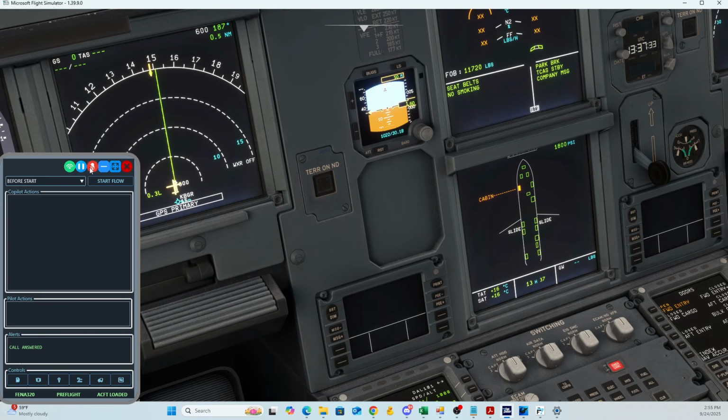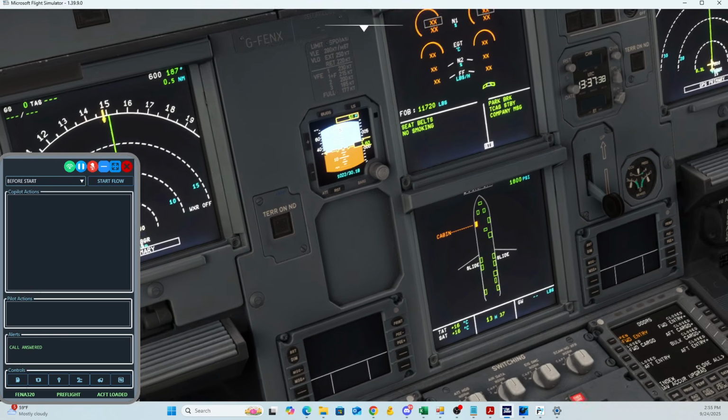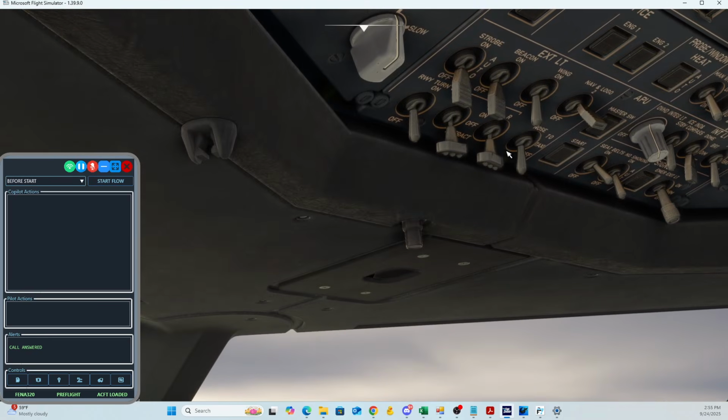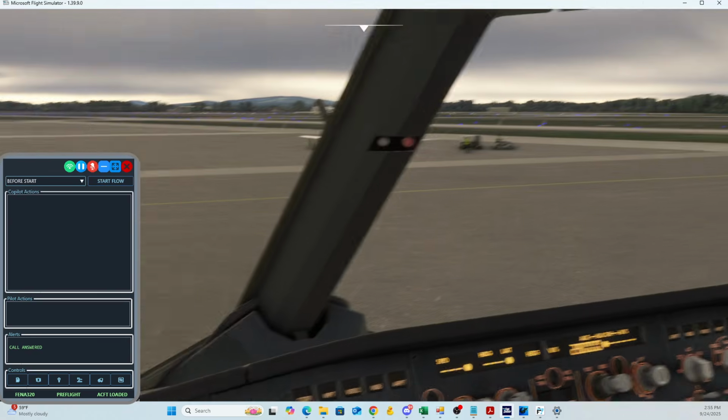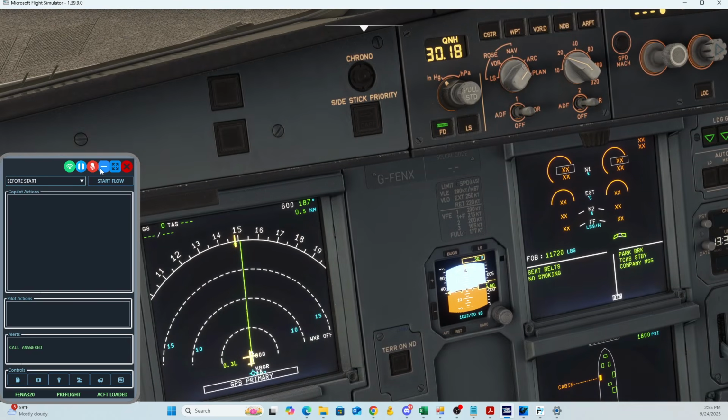We'll enable voice on the before start checklist just so you get a flavor. Every setting was set correctly. Why wouldn't it be? Because we had our first officer set everything for us. However, if it wasn't set correctly, you veterans know the co-pilot would just wait until you set that correctly. That's the difference between voice and button mode. If this is enabled and this is green, whether it's muted or not, you have to give a verbal command before the co-pilot will move to the next flow.